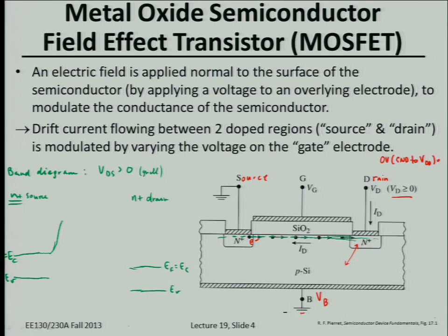So it'll be p-type. Let's draw something like this. I was trying to draw this so that clearly there's a potential barrier, because you have an N region and a depleted P region in the channel. So you have a potential barrier height for electrons going from the N-type region to the P-type region. But the height of that barrier should be less than the band gap energy, because it's maybe only very slightly forward biased. It's depleted, but it might not be strongly p-type. Does that make sense?